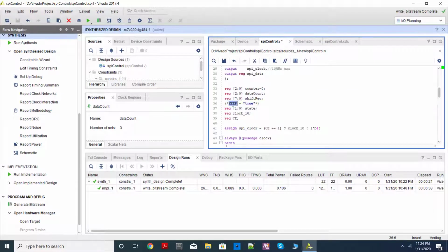Now these attributes have nothing to do with Verilog. The attribute syntax has to do with Verilog, but keep is a type of attribute that has nothing to do with Verilog. What attributes are available depends upon the particular software you are using. This keep attribute is understood only by Vivado. If you use the keep attribute in Quartus, the one for Intel, it might not understand. It will have some other attribute which Quartus understands. So keep that in mind.